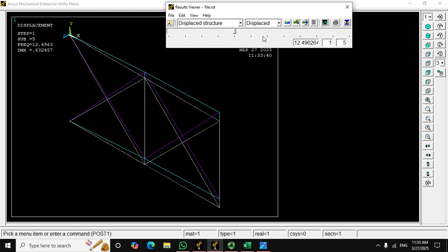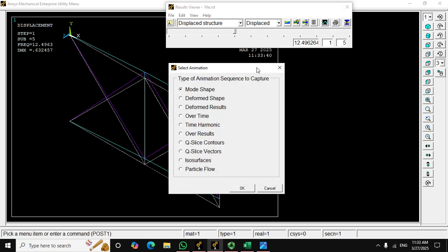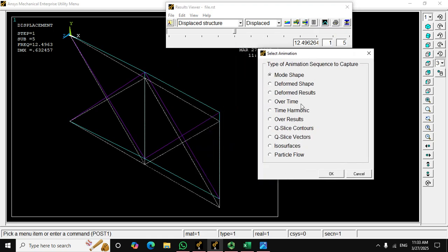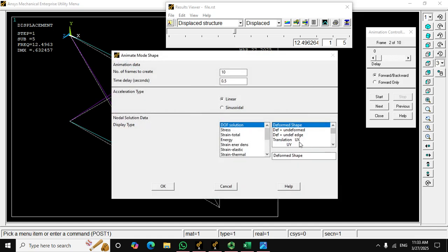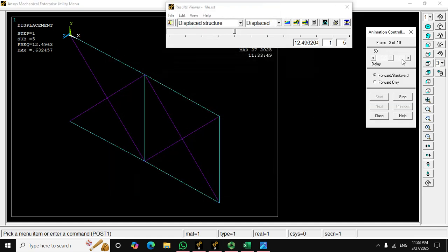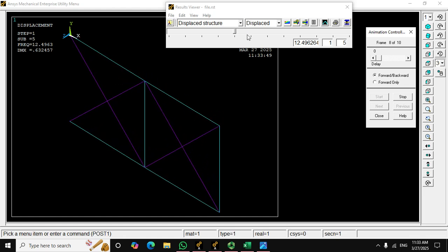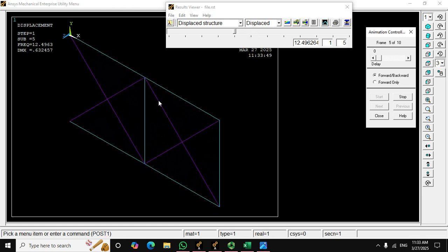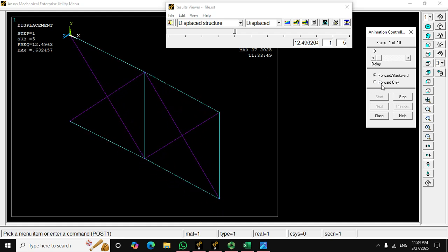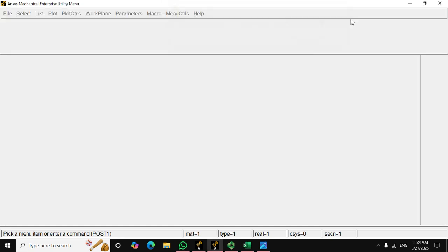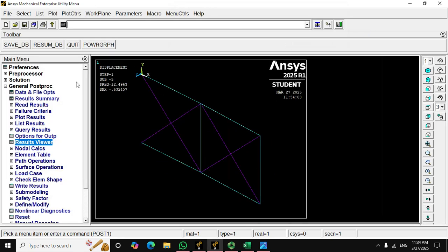Now we're gonna come to 2D. So when it comes to 2D, now we have the frequencies and mode shapes I already had after I had constrained z. Yeah, so the remaining frequencies are what we saw before. Alright, so I just wanted to show you. What we learned here is that the number of frequencies and number of mode shapes is gonna depend on degrees of freedom.